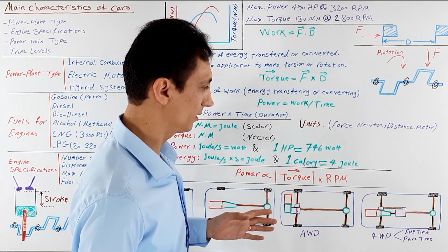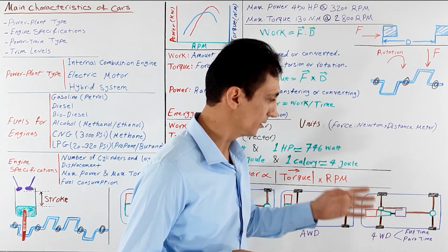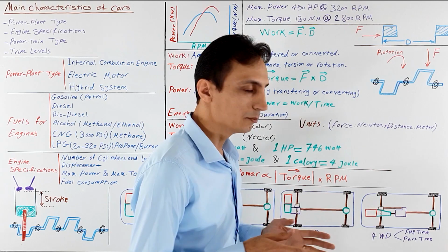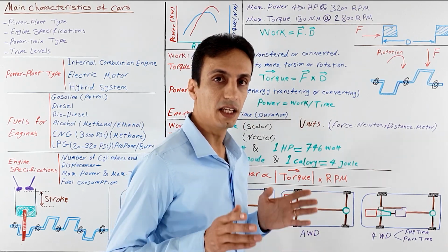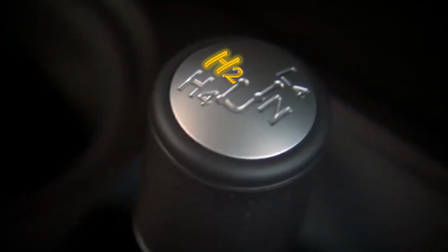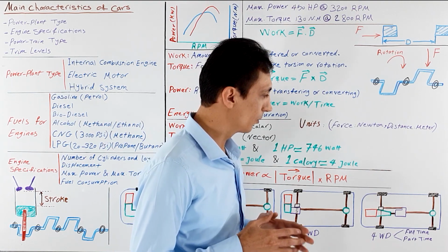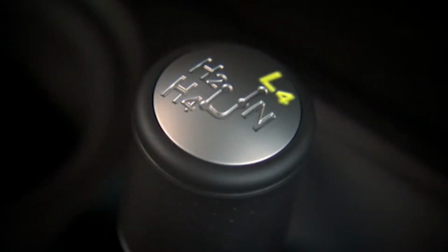Also, in the market there is another design for four-wheel driving, that is the part-time four-wheel drive system. And this system is a little more complicated in the way that engagement works in the transfer case, and we usually drive this system in two-wheel drive mode, but there is a button or shift stick for the driver to go into four-wheel drive in high speed or low speed mode.